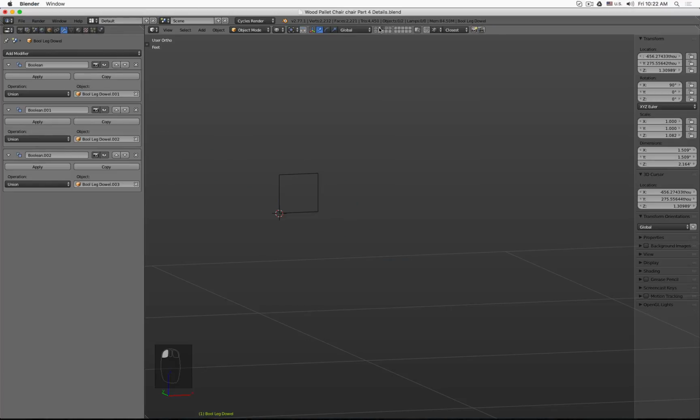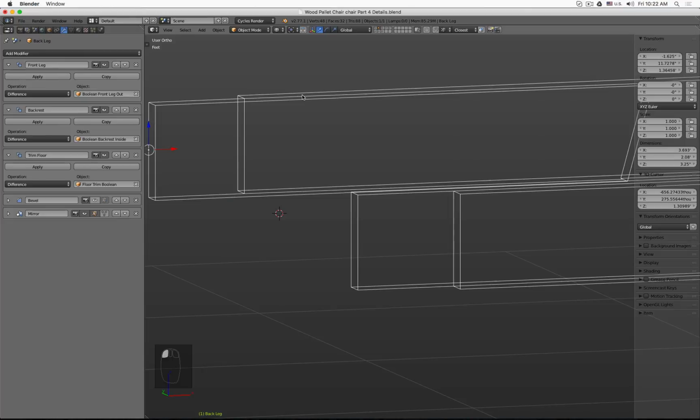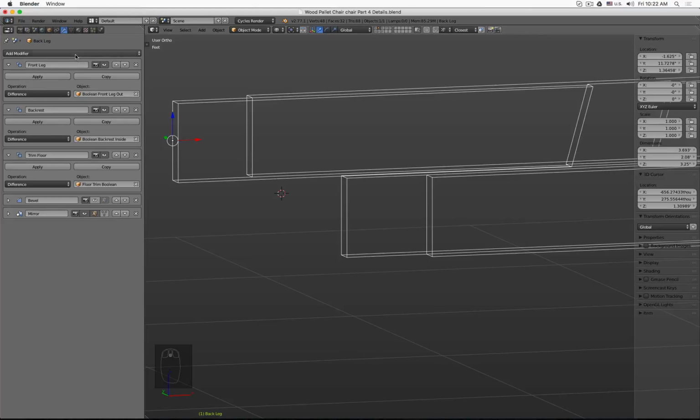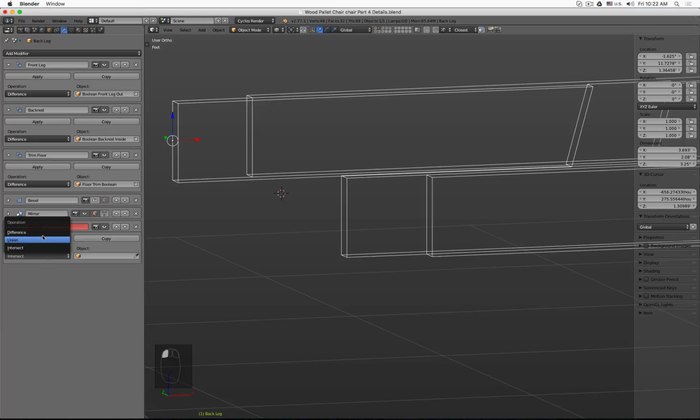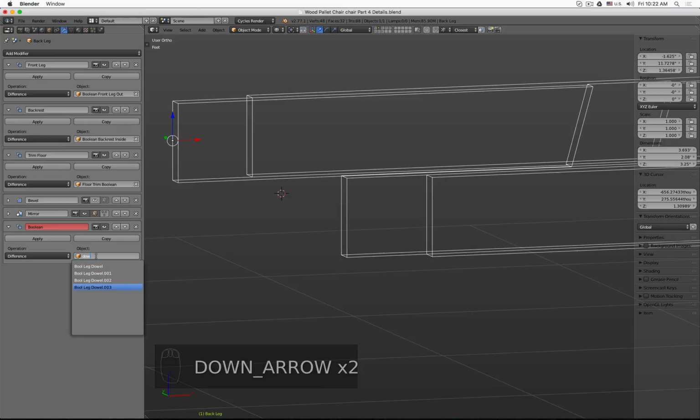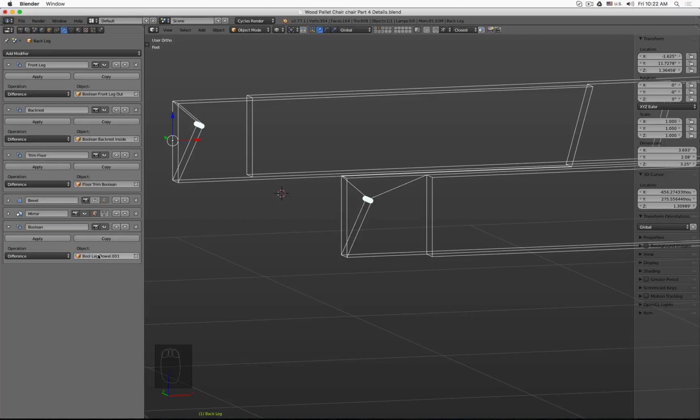And what I can do now is simply, when I go to this and I say at the end Boolean difference, and then I select this object, so not the other two, because if I select this one, you see it only gives you this one cut or this cut.